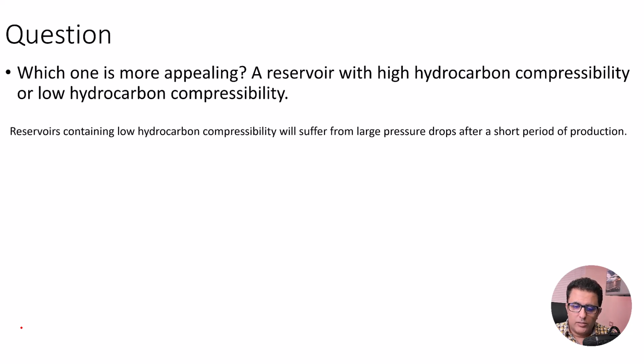In other words, once we start producing hydrocarbon, the pressure will drop significantly, and we know that the fluid pressure is the major driving factor for us to produce hydrocarbon from a reservoir that is 1 or 2 kilometers below the surface. And that's the thing I'm saying: gas has very high compressibility, which means that the pressure drop for a gas reservoir is not as significant as for an oil reservoir. Let me explain it here.